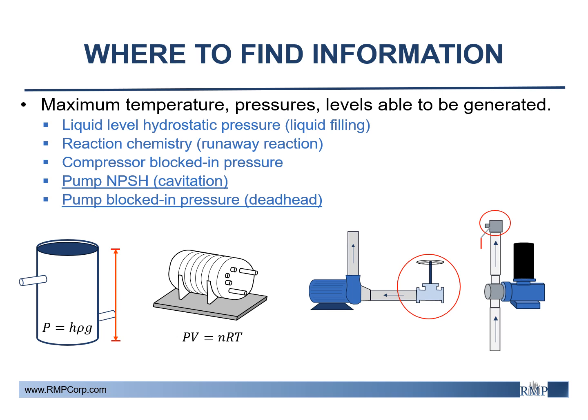We may need pressure and temperature calculations from reaction chemistry for runaway reaction scenarios. Compressors can be damaged if blocked in to certain pressures. Pumps have NPSH requirements that, if not met, lead to cavitation, and pumps can also be blocked in and be damaged due to deadhead.